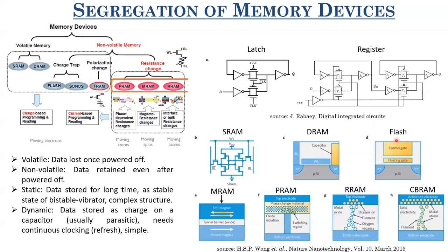I mean, it would be too much to comprehend in the first go, but you just think of it like this. You have a material, you have several of these individual dipoles there. By applying a pulse, you can align these dipoles in a certain direction. When you have not applied a pulse, these dipoles are aligned randomly. You have a net dipole moment, or a net charge, which is smaller. But once you apply a pulse, you have aligned them in a particular direction so that effective polarization has increased. So since the charge has increased in your oxide stack, what you are essentially doing is changing the threshold voltage again, and you are essentially encoding some bits there.